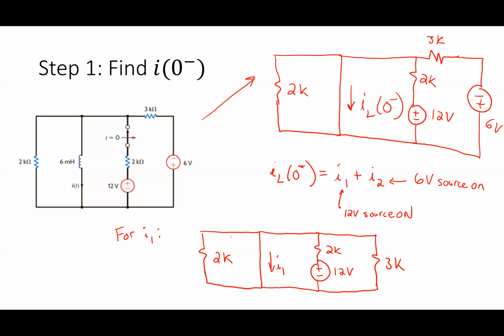So the way I do that real quick is I'll do a KVL around this loop right here. And I'll say 0 equals I times 2K, where I is the current in that 2K resistor. So what does I have to be? 0. All right. So remember the other day I said KVL, KCL, Ohm's law. That's it. That's all this class is. Okay, that's still true.